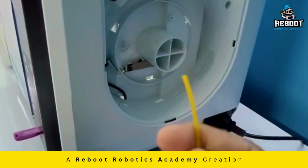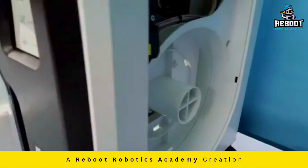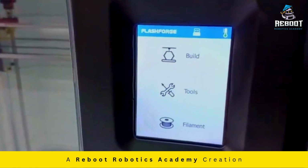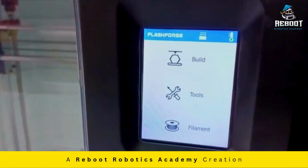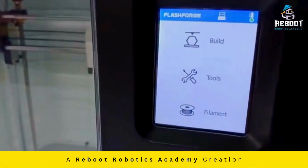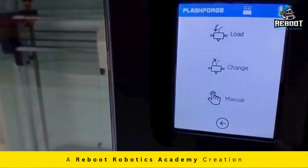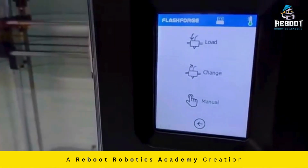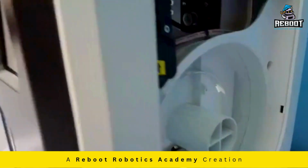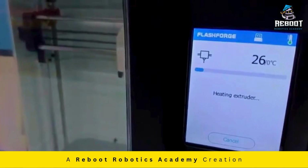So at the very beginning, we will be attaching this filament to the 3D printer, and for that we have some options over here. At the top we will see build, which means it will ask you to print things. Then there is tools, but for adding the filament to the 3D printer, we will go to the third option. Here the options are load, change and manual. Since we are not using any filament right now, we are adding a new filament, so we will go with load.